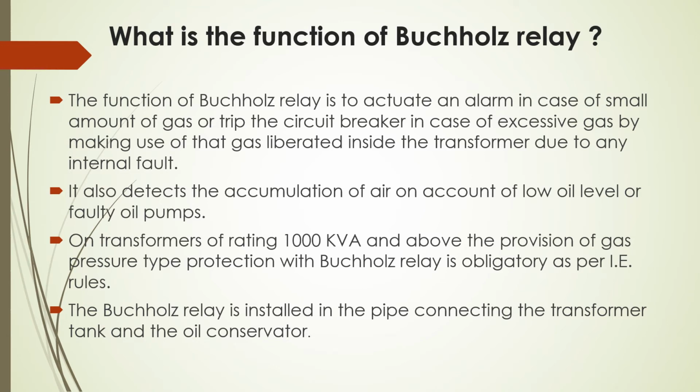On transformer of rating 1000 kVA and above, the provision of gas pressure type protection with Buchholz relay is obligatory as per IE rules. The Buchholz relay is installed in the pipe connecting the transformer tank and the oil conservator.